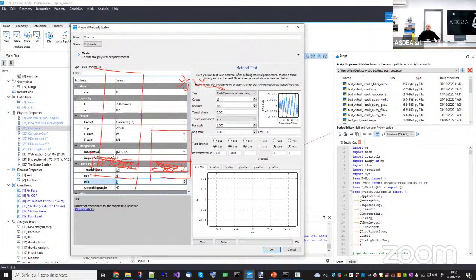Now the concept is that since the physical size of the crack is the same, if you take the total displacement here, which is 0, 0, and the entire displacement jump concentrated in this point, you will have the same displacement jump on a smaller element. But if you take the strain, you will divide the displacement jump by the total length here, and you will do the same here. But here the deformation will be much higher, simply because you divided the same displacement jump by a smaller length.